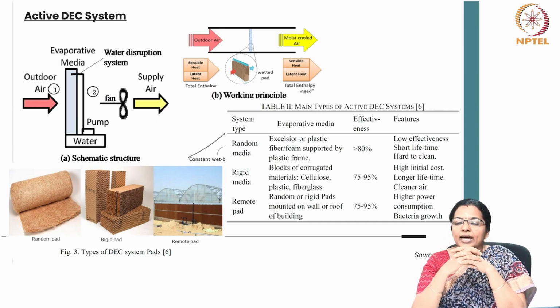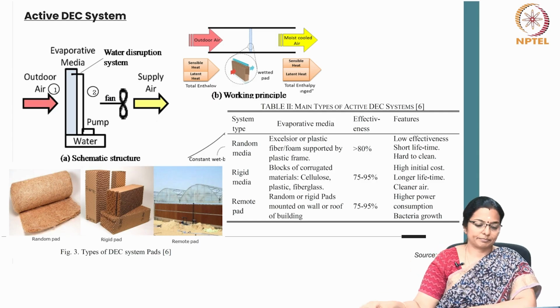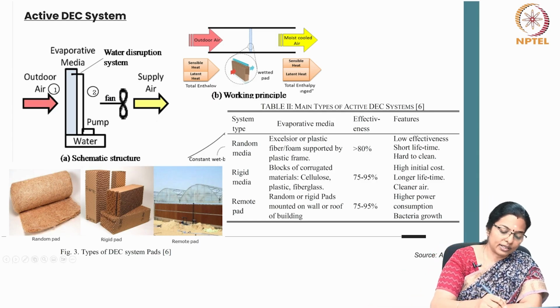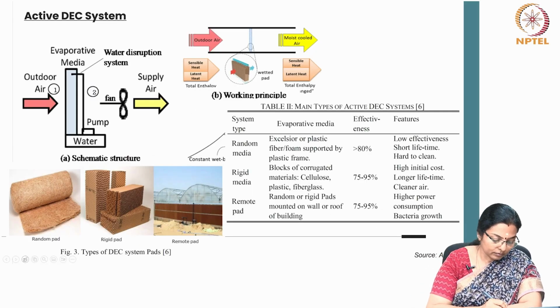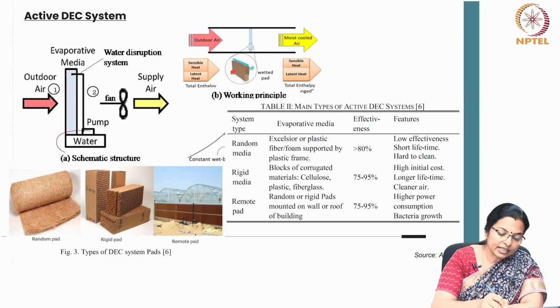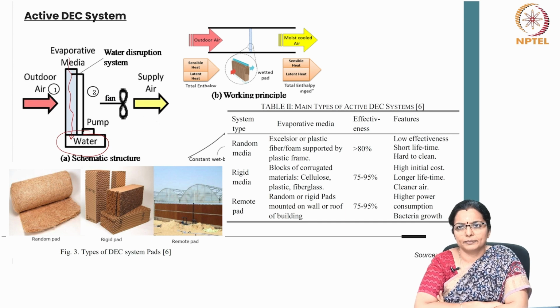It requires a fan that pushes air through the wetted medium, a water tank to collect the water that passes through the medium, a recirculation pump and a water distribution system.